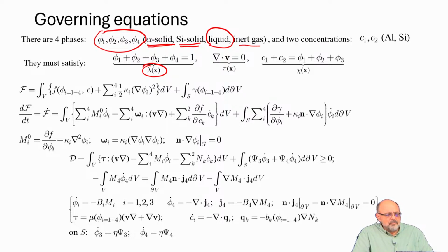Now, pressure will not play much role here, and the change of volume is not very important. I do have a few percent change of volume, liquid to solid, but because there are no mechanical constraints which would prevent shrinkage and growth, it's a flow. There's lots of fluid. I don't care about the change of volume. So I don't care about elasticity in this problem, which makes the problem much simpler, right?